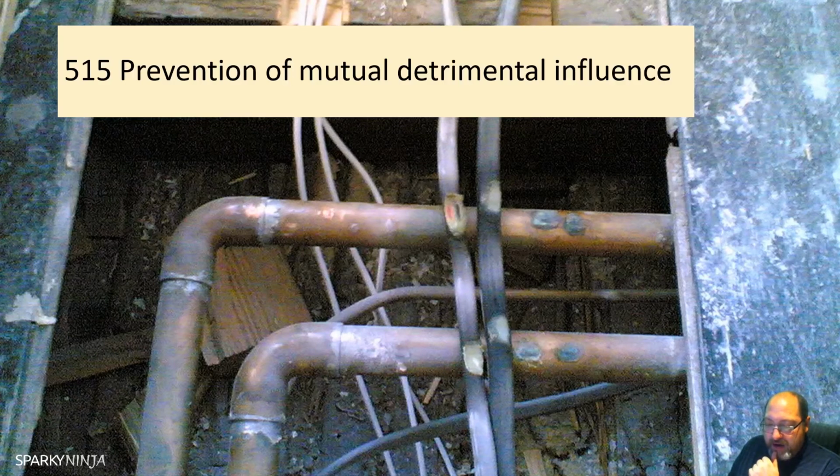Where equipment carrying current of different types or at different voltages is grouped in a common assembly, such as a switchboard, a cubicle, control desk, or whatever, all the equipment belonging to any one type of current or any one voltage shall be effectively segregated wherever necessary to avoid mutual detrimental influence. So this is where, within an installation, you can have band 1 and band 2 circuitry, and then there's a risk of induction of the voltage from band 2 to band 1, which can be a problem.